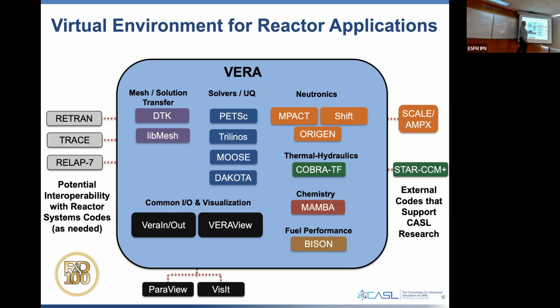For thermal hydraulics, the CTF code is what we have. It is that sub-channel thermal hydraulics capability. It can be run in assembly-sized mode, but usually for us, we are running it with every individual channel resolved. But CTF standalone doesn't have the information it needs to be able to model these things. So how do you understand the mixing after a grid spacer? How do you understand the redistributions and the pressure drops? And so it uses the STAR-CCM+ CFD code to run a whole lot of CFD calculations to define the models that are built inside of CTF.